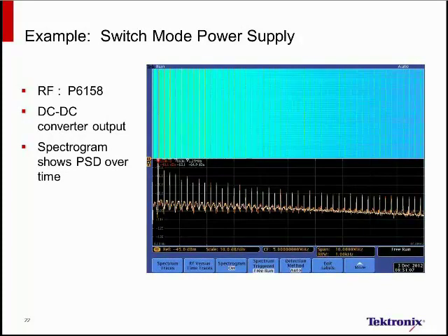The second thing the spectrogram gives us the ability to do is look into the noise floor a little bit more clearly than a regular spectrum analyzer display. I can look for non-randomness in the noise floor to see how a signal is changing over time. For example, it's easy for me to see all of the vertical parallel lines from the harmonics of the switch circuit in the DC to DC converter.